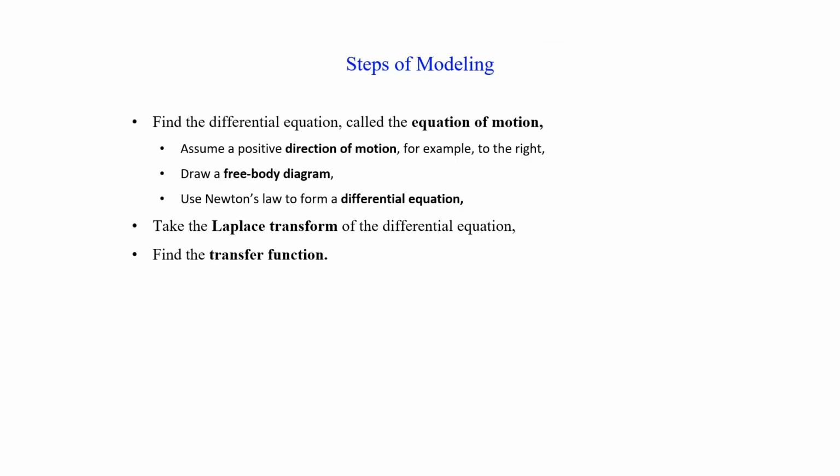So to model the mechanical systems, we will employ the following steps. Firstly, we will find the differential equation of the mechanical system, which is normally called the equation of motion, or generally written as EOM. And to find the equation of motion, firstly we will assume a positive direction of motion, for example to the right, and it is generally expressed as